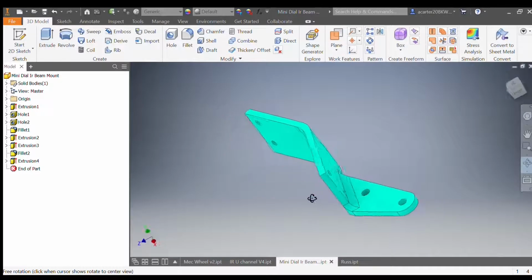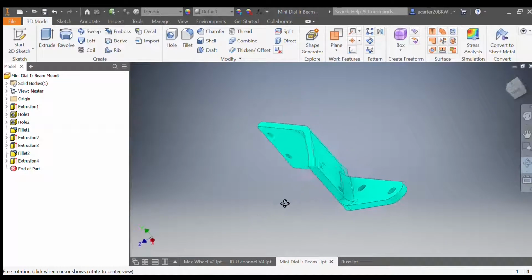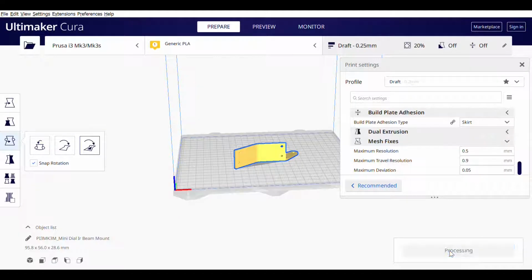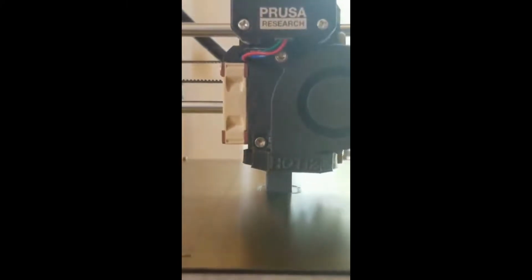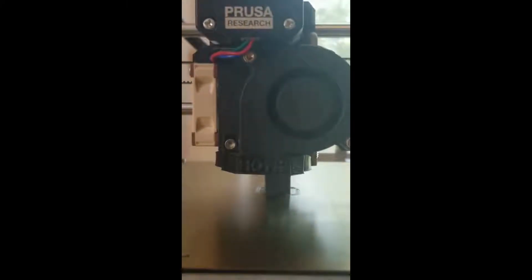Hi, I'm Anna, and I'm a senior on the team. An area of our team related to CAD is 3D printing, so I'll tell you a little bit about it. We use CAD to design the part that we need to 3D print, then use a slicer program like Cura to make the print settings. Then we save the file to an SD card, put the card in the printer, and select the file we want to print. The printer heats up plastic filament and extrudes it while moving its axes to form layers.